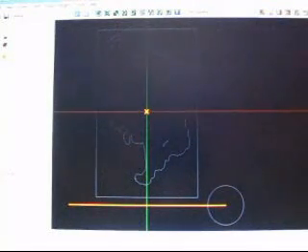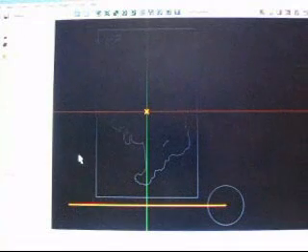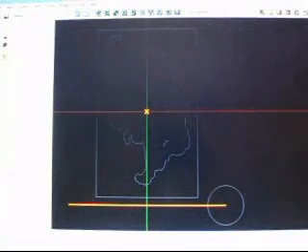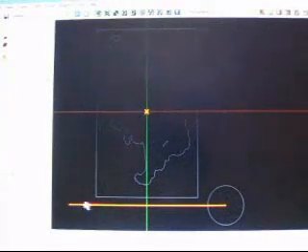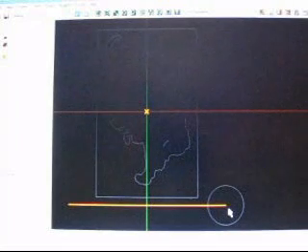Now my cut width is going to be 6.25 inches, 6 1/4. So 6 1/4 away from this is my overall cut width, okay? And it's going to step in increments and step over at 40% of the tool. So it's going to go out to here 6 1/4 inches and then come in at 40% of the tool at a time till it finally reaches this line over here. And that's the wall that it's going to end up on.